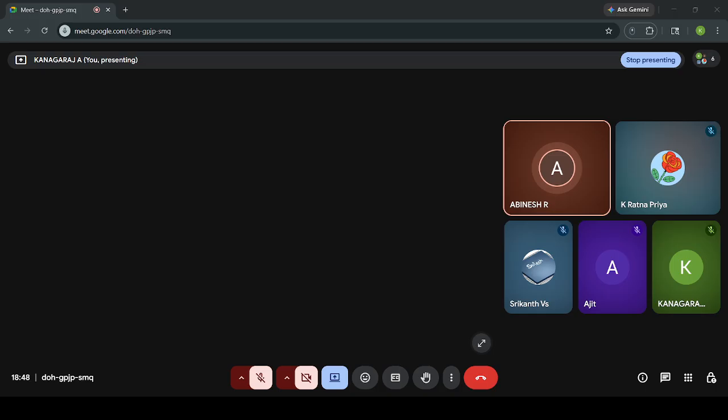Next one is rework challenges. Repairing can also be a challenge. Package cost: a ball grid array can be the most expensive compared to others. Next one is testing complexity. Testing BGA packages for faults or defects can be more complex than testing packages with visible leads. Visible leads, such as SOT. SOT is small outline transistor.